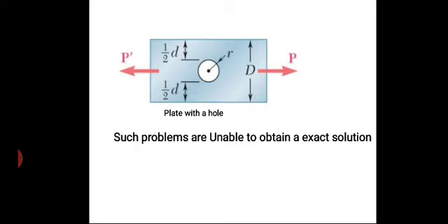In such problems, I cannot apply stress equals force by area, because the material may not have a uniformly distributed area, and we cannot say the stress is directly proportional to the applied load, because of the circular hole created at the center of the plate. So in these conditions, it is very difficult to get exact solutions.